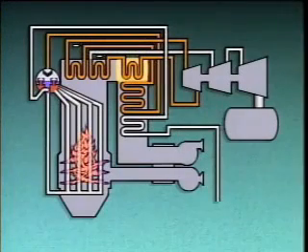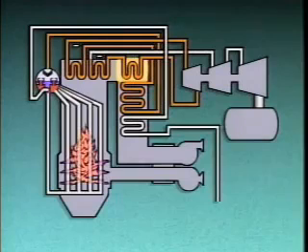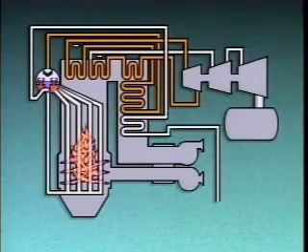For example, this boiler has a primary reheater that the steam enters first as it comes from the high pressure section of the turbine. After the steam flows through the primary reheater, it moves on to a secondary reheater. An attemperator, located at the beginning of the secondary reheater, is used to control the final temperature of the superheated steam leaving the secondary reheater.